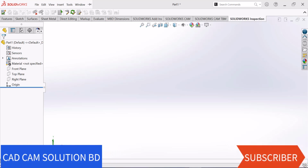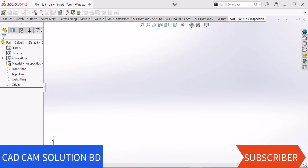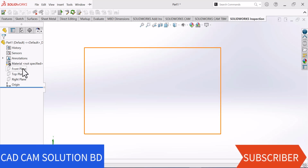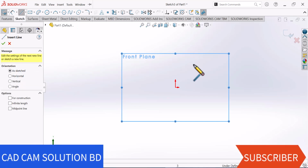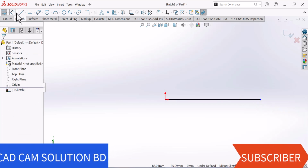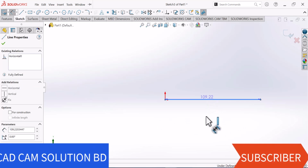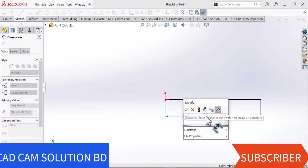Today I am going to show how to revolve tools using SolidWorks 2025. We'll learn it. First of all, I am going to select plane, front plane and sketch. Now go to line tools and select horizontal line. Now go to smart dimension. Now give the value this line dimension 85. 80.